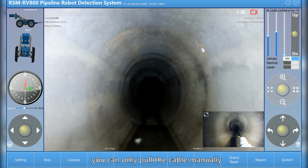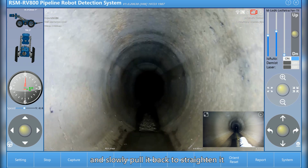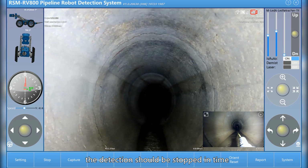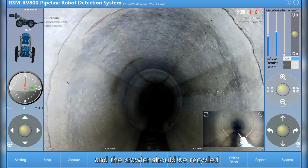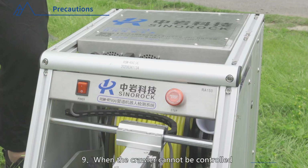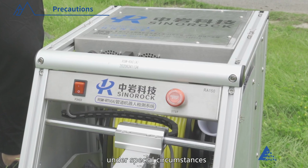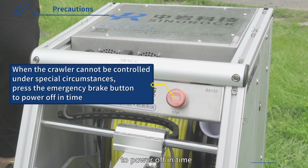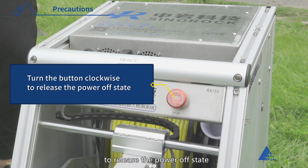If rollover, you can only pull the cable manually and slowly pull it back to straighten it. When the detection conditions are difficult, the detection should be stopped in time. The video should be saved and the crawler should be recycled. 9. When the crawler cannot be controlled under special circumstances, press the emergency brake button to power off in time and turn the button clockwise to release the power off state.